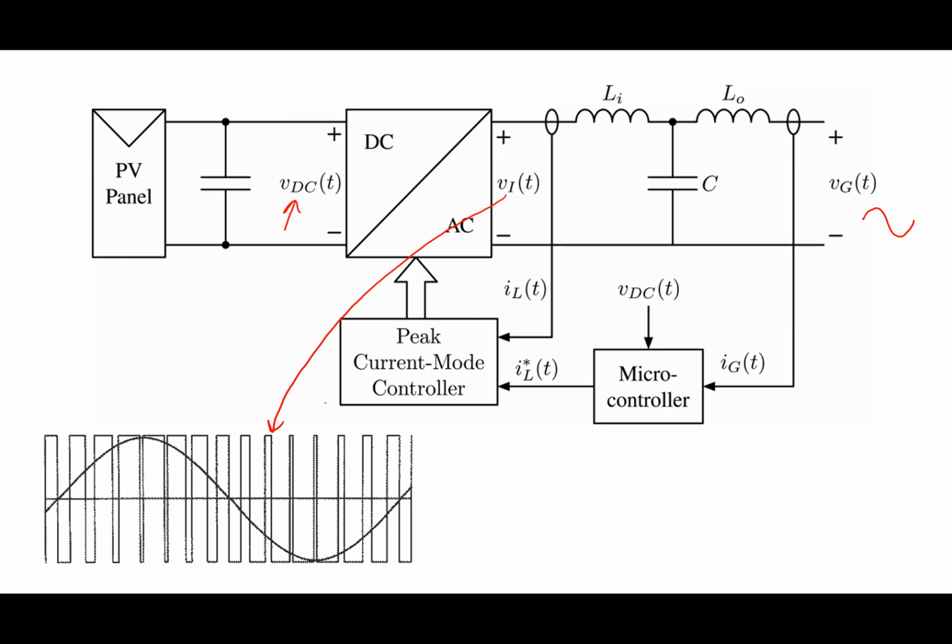It's periodic. But if I understand what's going on here, it's just something called pulse width modulation. And if I knew the Fourier series for that odd looking square wave, then I could figure out how to drive this thing so that I connected to the grid properly over here. So it's a useful analytical tool for us, this whole Fourier series concept. It helps us to do a lot of stuff from a design perspective that we couldn't normally do otherwise.